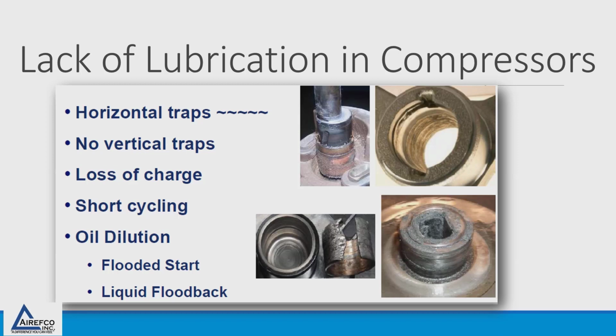Pictures show the lack of lubrication in a compressor. Causes for this could be the improper use of traps, the loss of a refrigerant charge, short cycling on the system, and oil dilution caused by flooded starts or liquid floodback.